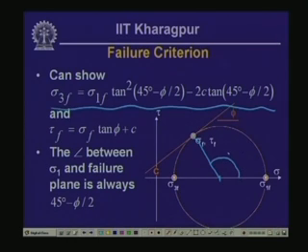So this angle here is equal to 90 degree plus phi, and from the discussion that we had on Mohr circles the other day, you can imagine that the angular spacing between the state of stress represented by sigma 1f and the point of tangency is going to be given by half of this included angle, which is 90 degree plus phi.